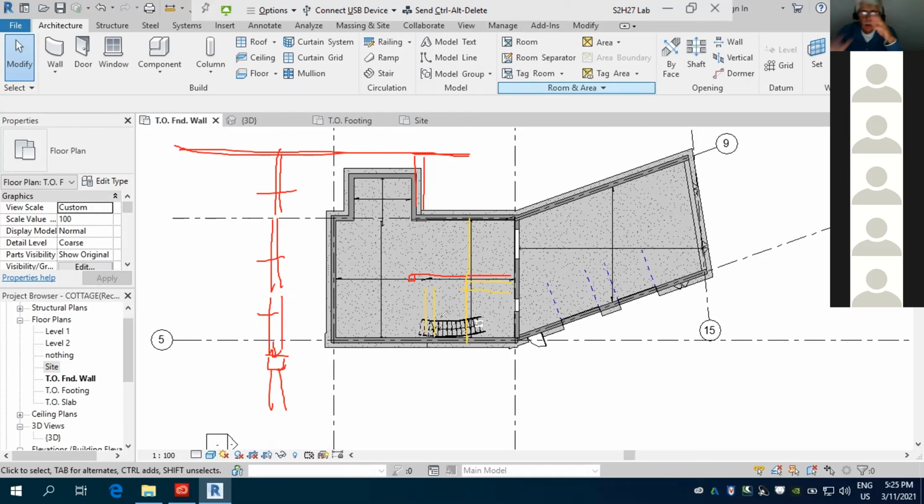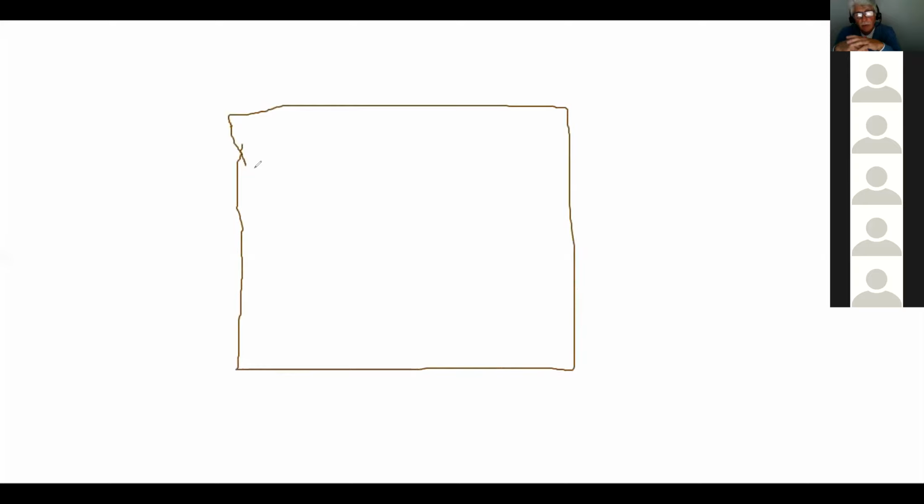Okay, I understand. But see, Brandon, you have to draw what's existing. Whenever you're doing any renovations, you have to draw what's existing so that you can get an idea of how the structure might have been built. You understand? Because me looking at this is very misleading. This is what you want to do, but it doesn't mean that you can do it. It doesn't mean that you can all of a sudden take away things, and then realize you're taking away columns, or columns that are coming down through the walls. You might not be seeing them, and then all of a sudden your whole analysis is going to be incorrect. You understand?